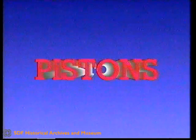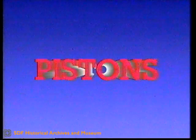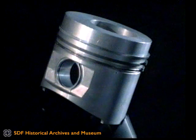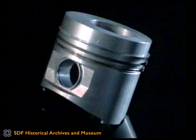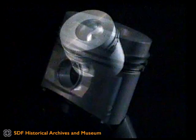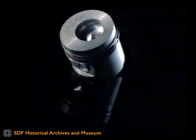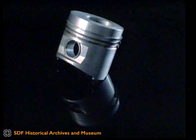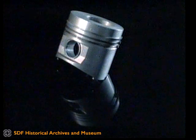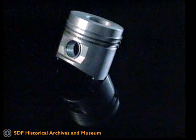Pistons are of a light aluminium silicon alloy. Play between pistons and cylinders remains constant under temperature variations. Less friction between pistons and cylinders, improved heat dispersal, less incrustation, livelier engine performance since the lightness of the pistons allows for more rapid acceleration, longer service life.